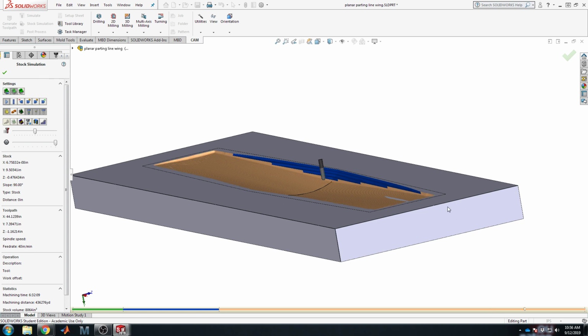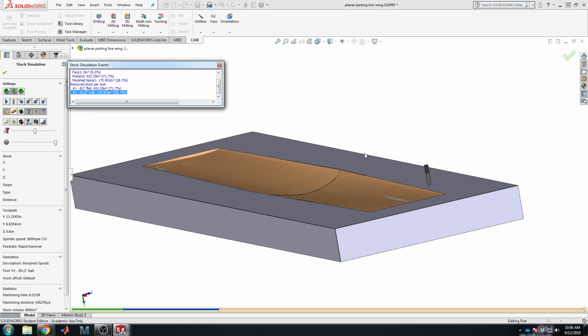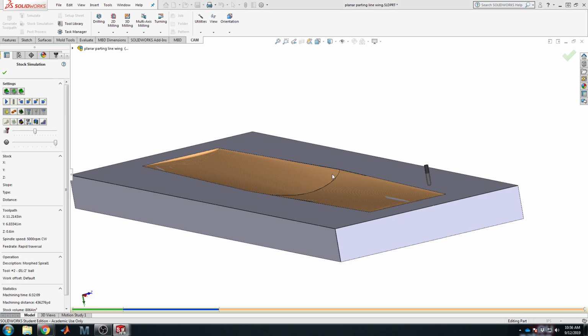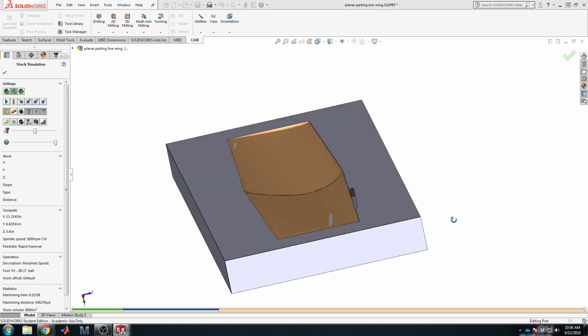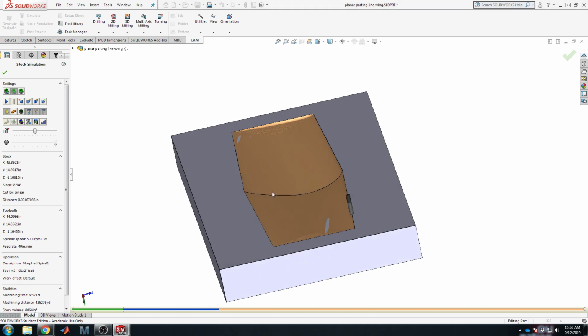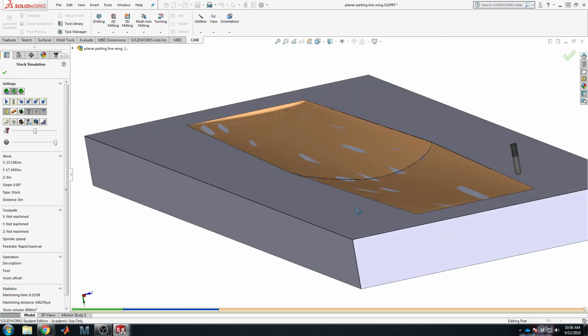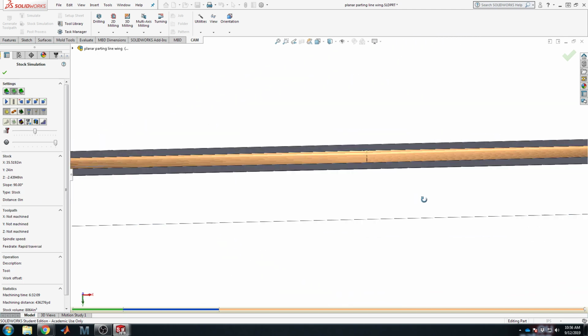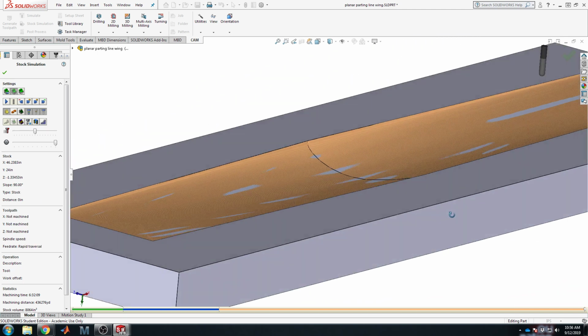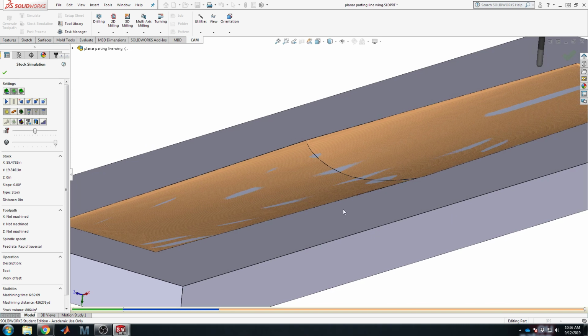These simulations are also really valuable for checking for conflicts. This is also the place that if you did define a model for the CNC machine cutting head, you could check for any sort of machine collisions. But this is the shape we should be left with. Notice it also color codes the surface by which operation it's cut by. In this case, there's a bit of Z fighting between the gray part and then the tan finishing pass. But overall, that is a really good surface finish.